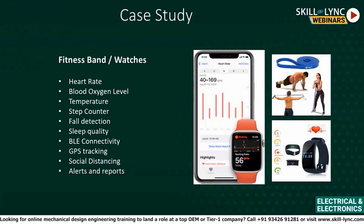What do you mean by memory unit? So what happens is, let's say I have a temperature sensor. Let's say I have 30-40 sensors interfaced to my controller, and I want to monitor and read data from all those 30-40 sensors simultaneously. So instead of reading simultaneously, we can choose a sensor which has a memory device in it. We will send a command to the sensor. The command will be like, read the data, and instead of sending it back, store it in your memory itself, so that whenever the processor needs it, we are able to retrieve the data.